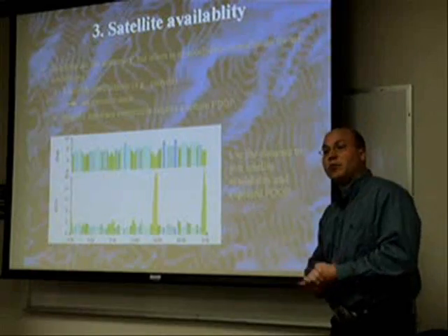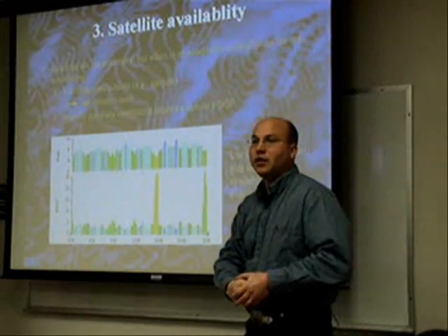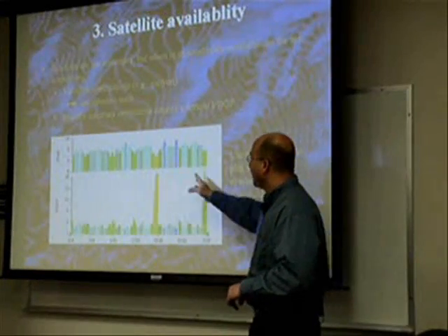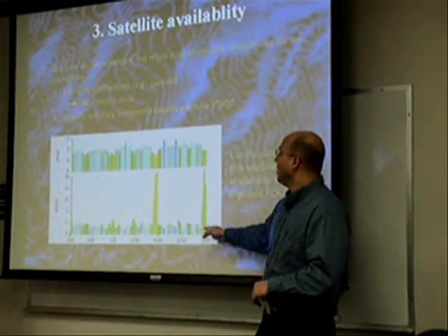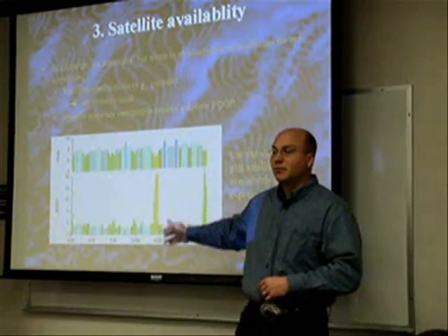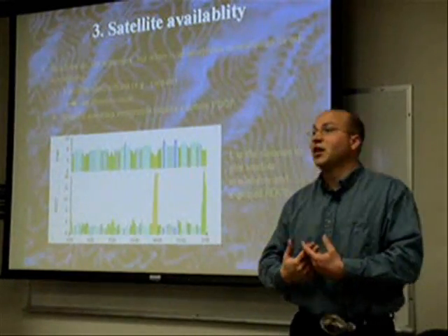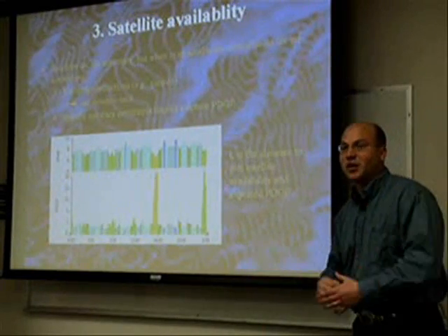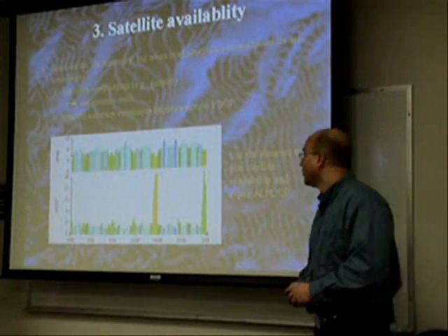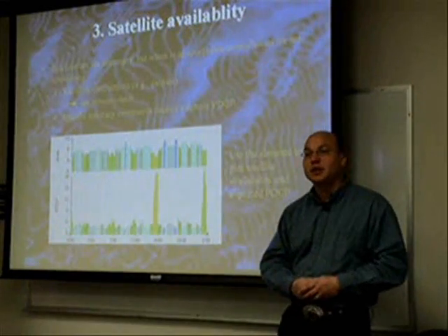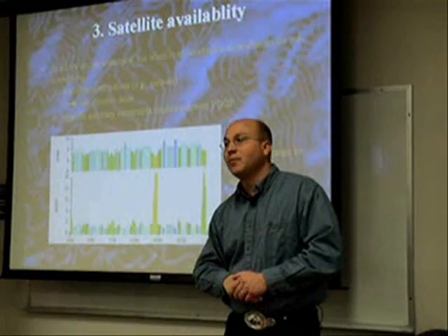So here, and Keith will show you how to do that using Pathfinder Office and the almanac, you can actually plan and see what PDOP you would expect out there. Of course, this planning cannot consider if there's, for example, a building or a huge tree with thick canopy cover, right? But this gives you a general idea what you can expect for a PDOP.